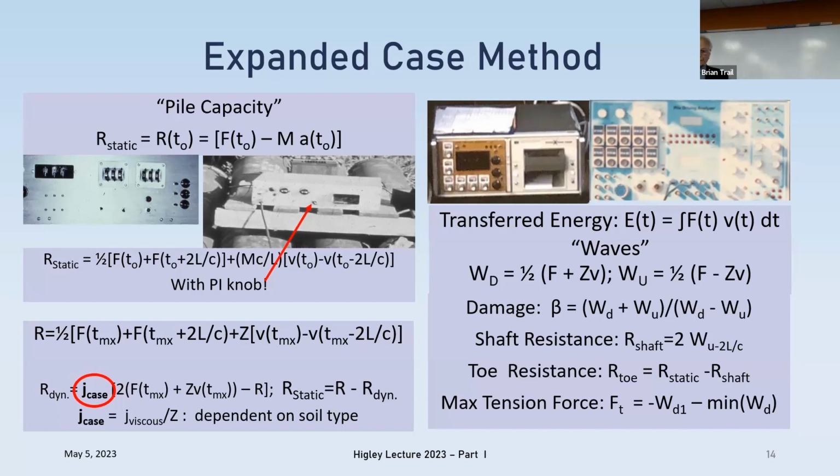And so if a pile had a damage or a reduction of pile impedance, as we would call it then, that could be quantified. We got, of course, the shaft resistance, and also printed out by the analyzer the tension force in concrete piles, which is very important. So that was quite a development once we had it in a digital form.